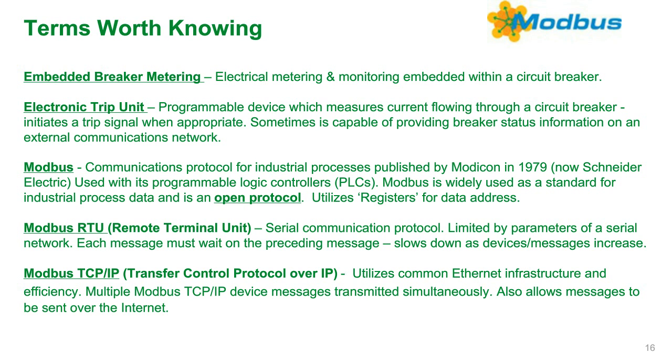So Schneider no longer controls it, but it was originated inside of Schneider back in the 70s. But it is considered an open protocol, meaning that there's nothing proprietary about Modbus. Every manufacturer knows what it is, how it works. There's nothing hidden. And the registers that are available to Modbus are something that is really cross-platforms and allows many different devices to be able to be connected.